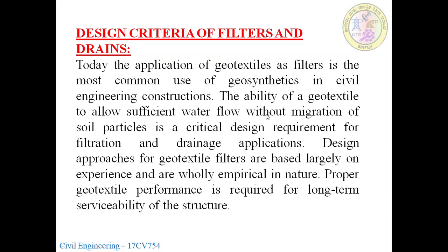Design criteria of filters and drains. Today, the application of geotextile as filters is the most common use of geosynthetics in civil engineering constructions. It is very famous. The ability of geotextile to allow sufficient water flow without migration of soil particles is a critical design requirement for filtration and drainage applications.